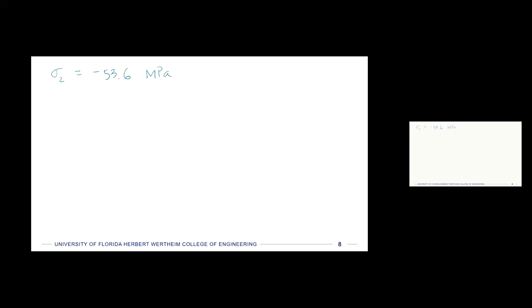All right, and I'm not going to write out all of the equations again, but this matrix will have the same values for all of the shear stresses. So I'm going to write them out. So 75, 55, and then the corresponding values as well, like this. And then across the center of that matrix is basically our principal stress. So minus 53.6.